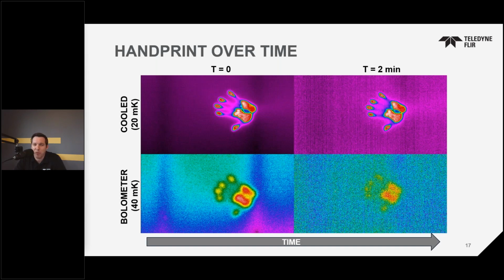This is really where you remind yourself of just how little heat was actually transferred and just how sensitive these cameras really truly are. In this demo, you're going to see how the photon counter on the top compares with the bolometer at the initial touch. The bolometer is displayed on the bottom. You can see so much more detail on the photon counter image because each pixel is going to be reading smaller steps in temperature versus the noise, whereas the bolometer cameras experience a much harder time due to its more difficult signal to noise.